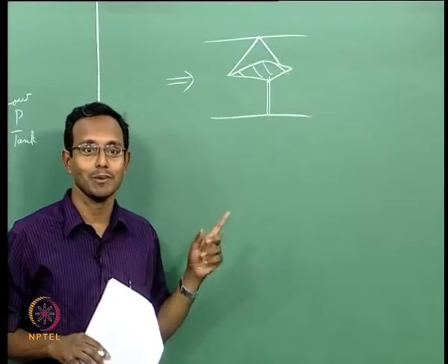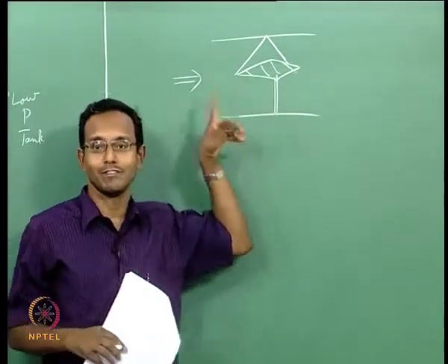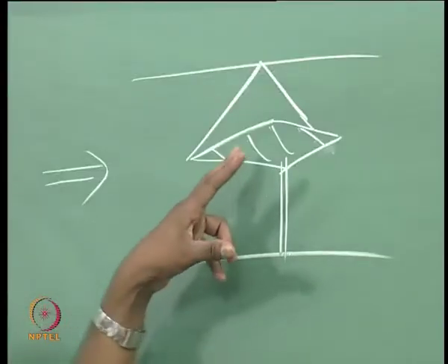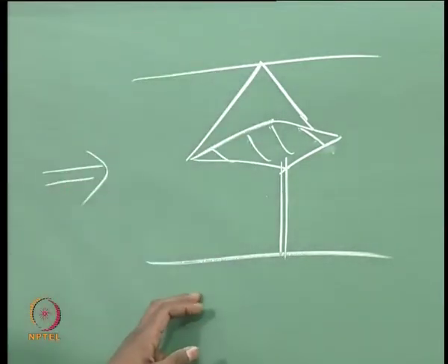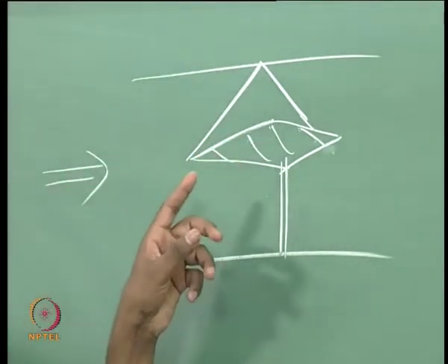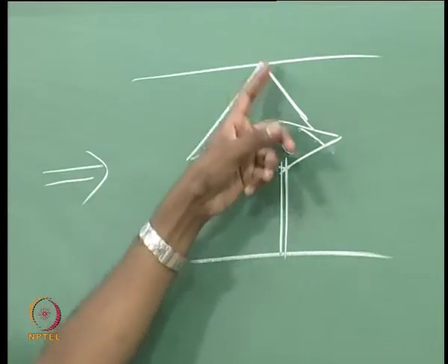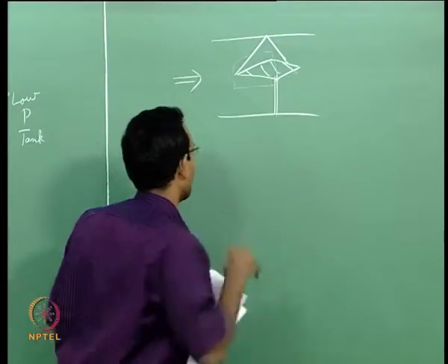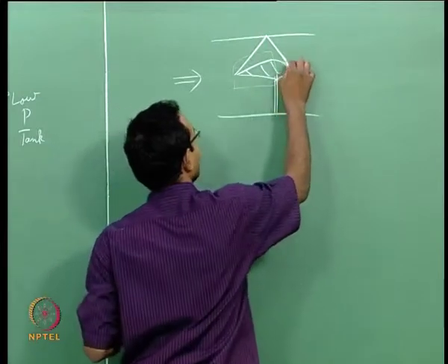That is one thing you have to think about when you are designing a model for a supersonic facility. This is not going to be there in your real flow experiments where there is no wall around it. So your model should be such that the shock that is going from the leading edge should not be reflecting back onto the model. That is one more thing you have to worry about. Of course, if you are interested only in the front portion, it will still work. Why? Flow is supersonic, things downstream will not affect upstream, assuming I am thinking only steady state problems. I keep mentioning this, steady state is very important there. So this is a bad thing about this model.